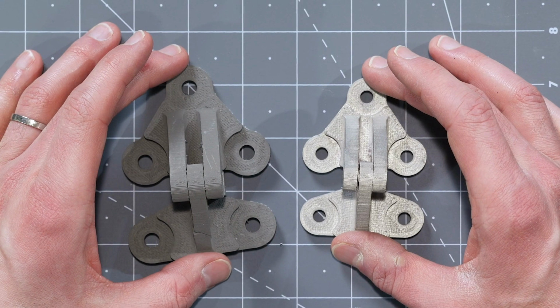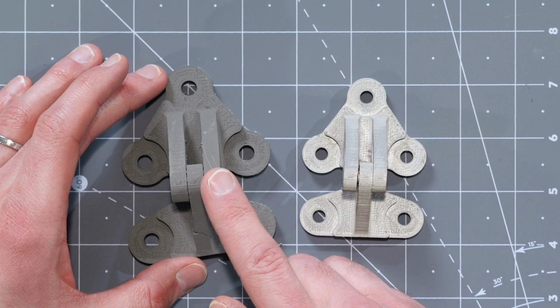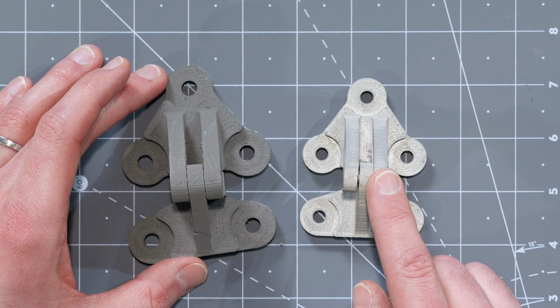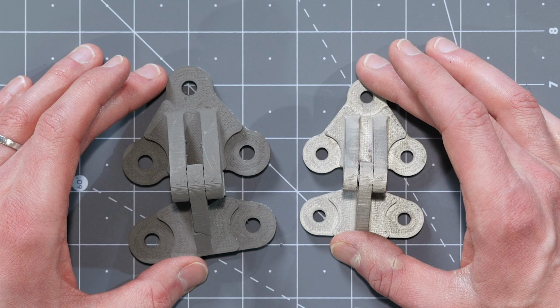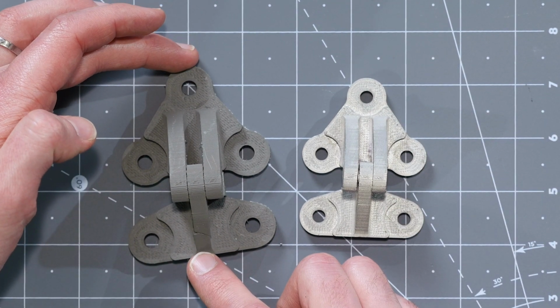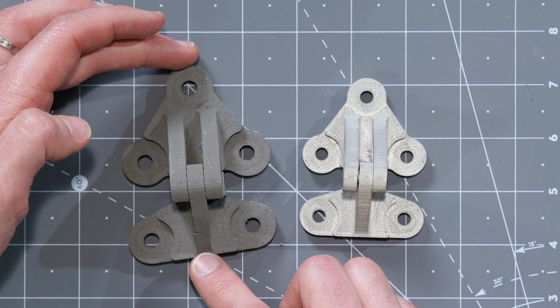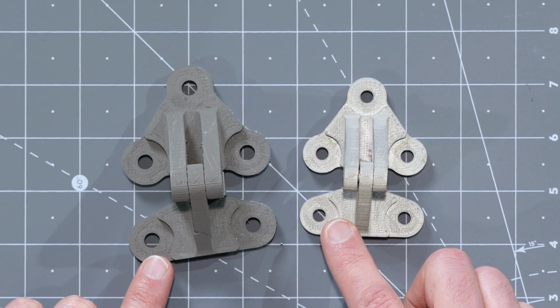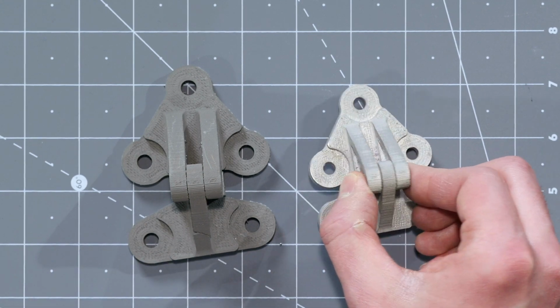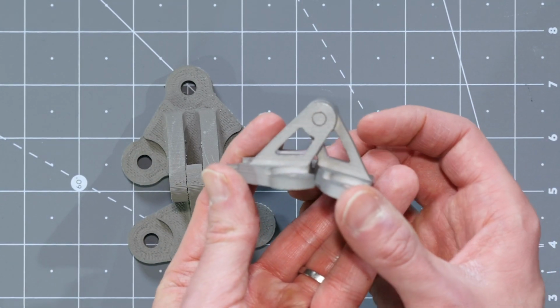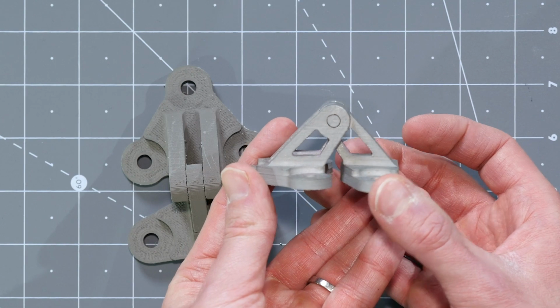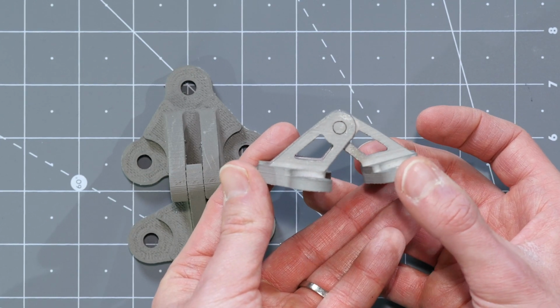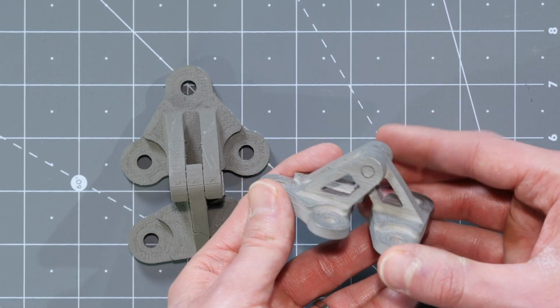The big difference you see here is not only in the color, plastic plus metal and finished metal, this is a steel alloy, but also in the size, because there's a lot of shrinkage, about 15% in each linear dimension as the part goes through the sintering process. And that's important to consider for accuracy, but can actually be quite repeatable and consistent. And as we like additive manufacturing for turning complexity into simplicity, this hinge was printed as a single component and has this single degree of freedom.